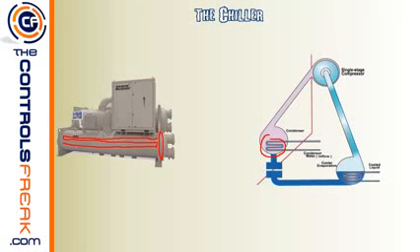So if you ever hear somebody saying they were changing out tubes or they have dead tubes in the barrels, these are the many tubes, and there's many of them. I've seen some chiller barrels that had literally 100 or more inside the chiller barrel. So there's tiny little tubes all throughout this chiller barrel, and that's where you get the water running back and forth through this barrel to do the heat transfer. So just a little bit of extra on the chiller. Let's move on to the next step.